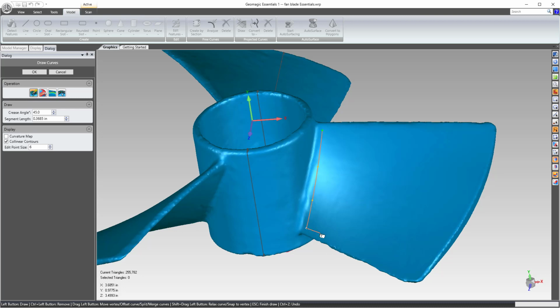So speaking of that, if I come over here and start drawing, I can create another spline and then hit escape. And then again, you can always come back and manipulate the curves and move them around. So a red node is an endpoint that divides up multiple splines. Essentially, if a spline has all orange dots, it's all one spline. And then a red node like that means that's the beginning and end of a spline.